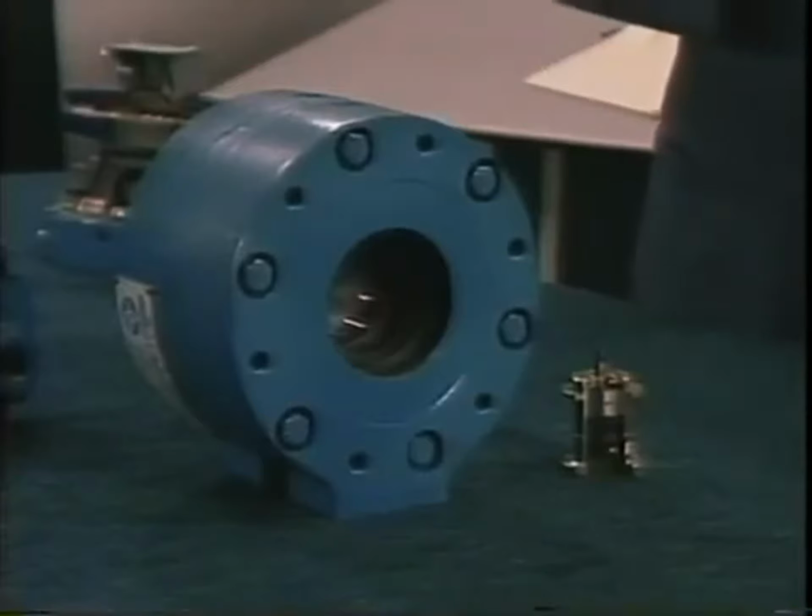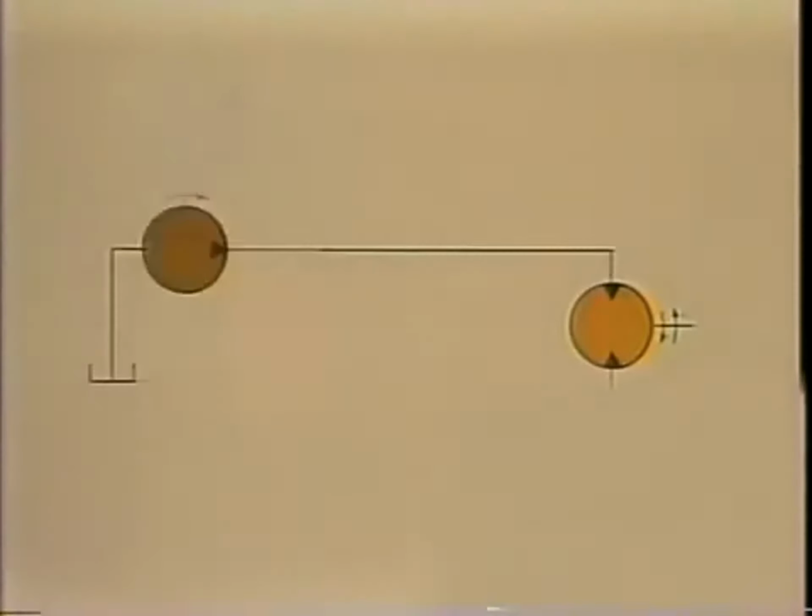The most common motors, and pumps for that matter, are vane, piston, and gear type. But since the functions of all three motors are the same, we'll just use the ANSI symbol to represent them. A motor is driven by the fluid. With pump flow connected to this port, the motor would rotate in this direction, provided, of course, that we have something to drive the pump.